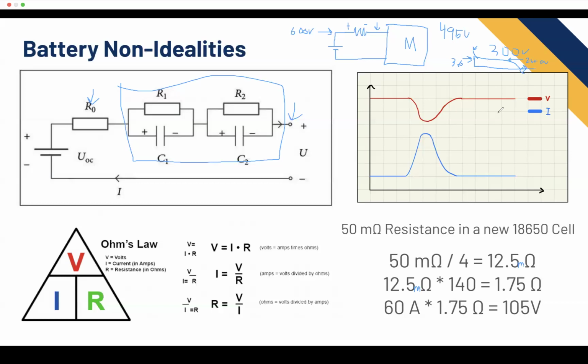But the voltage wasn't, well, the voltage was actually that low, right? But it was because the resistance, like we were able to source that much current, it could have kept going, but the system shuts off because it's like, hey, your voltage is too low. So the car shuts off. That's not good, right? If it's shutting off with like 30% left because we're browning out, then during endurance we are losing 30% of our capability on the bottom side. So you have to way oversize it, which we don't want to do, right?